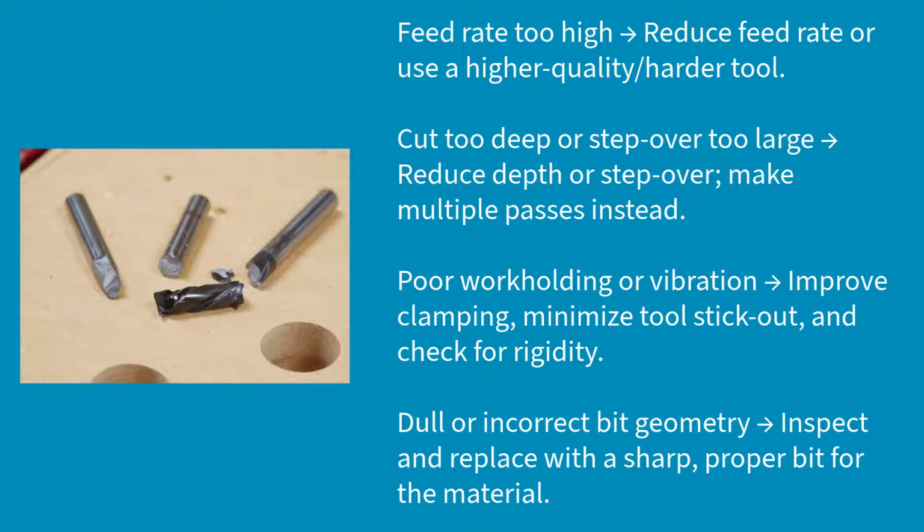And then oftentimes if your bit is dull, it can also break, so we recommend replacing it with a proper bit, or making sure that the bit that you have works well with your material. We have a video on bit types as well. We'll link that below as well, so you have that information.